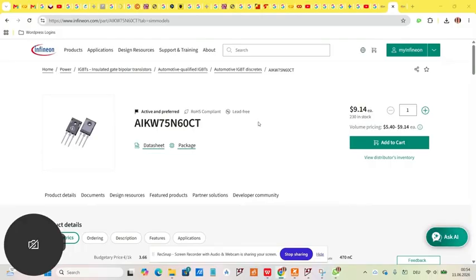My name is Joseph, and today I would like to show you how to add a SPICE model into LTSPICE, to add a symbol, maybe a transistor, into LTSPICE. When you look at LTSPICE, not all the transistors that are applicable to maybe high power converters are present there.